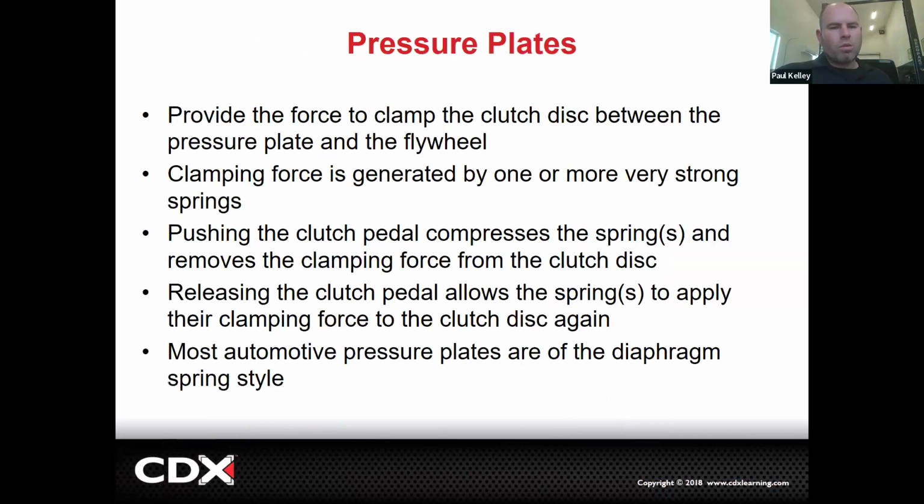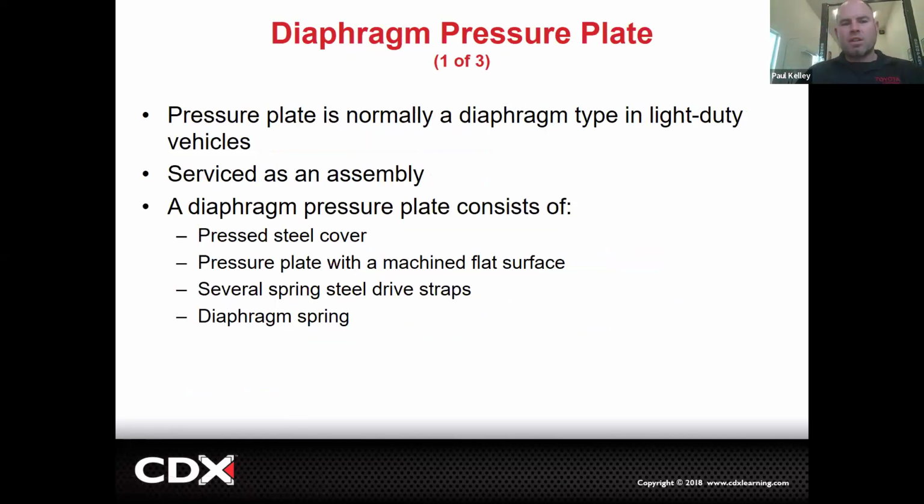Okay, and so we talked quite a bit about dampers already. And then again, it provides the clamping force. The springs can vary. Okay, so I want to show you the springs. All this is basically describing what it does. That's kind of what I described with my arms. But the spring type can vary. So like the diaphragm was pretty common. That's the one that we saw.